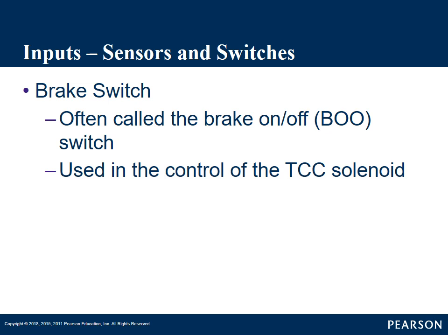It'd make that solenoid open up, and you could start it up, and most of the time it would be free and you could drive it. But once you got up to speed, it re-energized that solenoid, it would stick again, and you'd come to a stop, and it would kill the vehicle. Okay, so that's a big reason why we have a brake on-off switch.